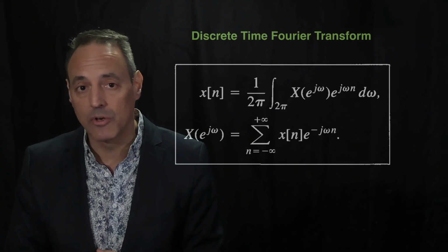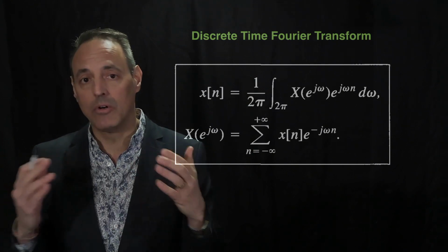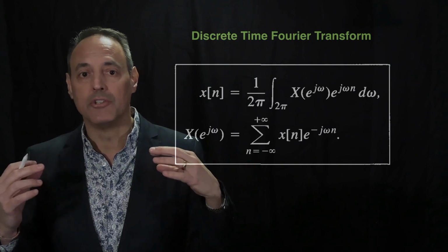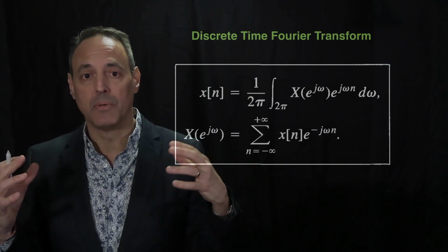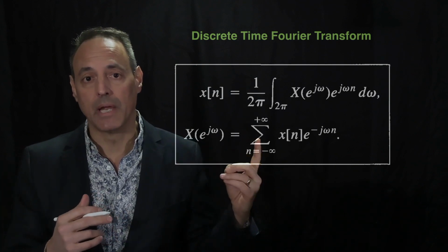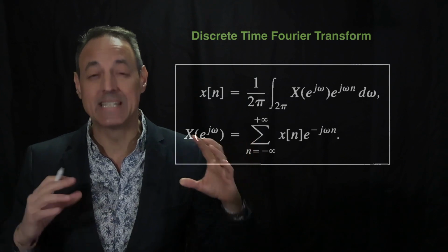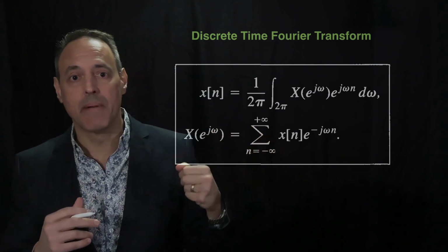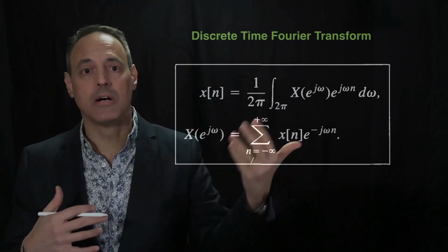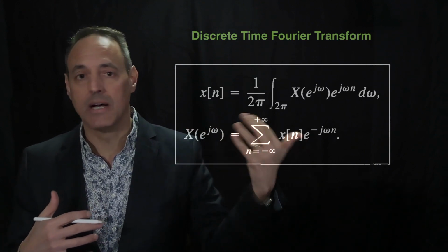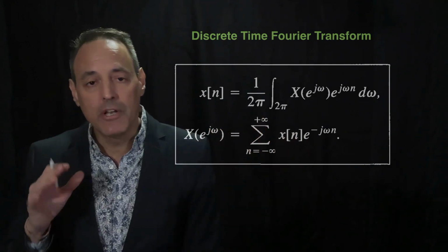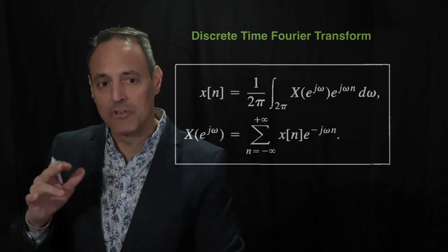A fast Fourier transform ultimately assumes that you have a signal which has a finite number of points, n. And then you think about that finite number of points being on a 2 pi periodic domain. Here's how you come in and out of the Fourier domain. This is a very important formula. It is the map to get in there and come back out. And remember, the entire goal is, once I'm in that space, I want to do some advantageous manipulations of my signal and then come back out, because the Fourier domain is a fantastic domain to do signal processing in.